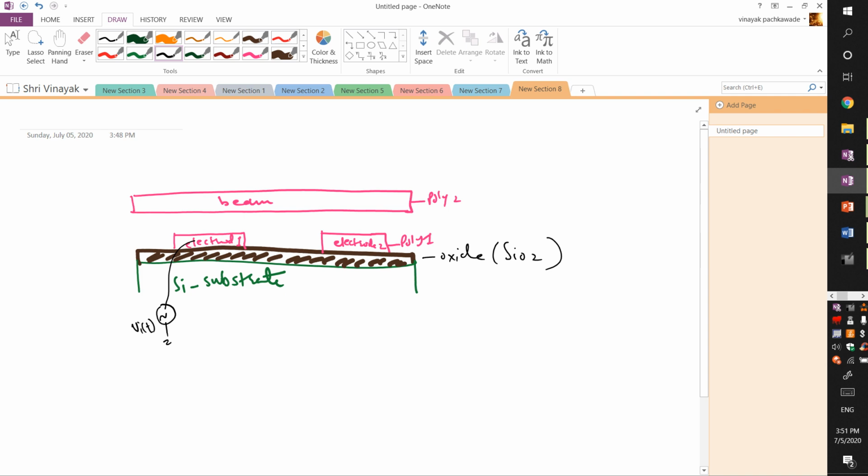All right, and then I have this. I apply the polarization voltage through this resistor to limit the current, and I have this voltage over here. So this Vi and Vp will exert an electrostatic force, which is attractive across this capacitive gap. So there is this capacitive gap over here. So let us draw it properly. So here is this capacitance. So let's say this is C1, and there is another capacitive gap right here, and this capacitance, let's say C2.